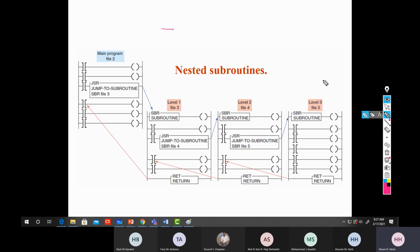Also, it could be nested like this. For example, you execute the jump to subroutine 3. So here, file 3. Then you execute here, and assuming this instruction is on as well, then you go to subroutine file 4. So this is file 4. You execute here, so then you go to subroutine 5. So this, we call it nested.